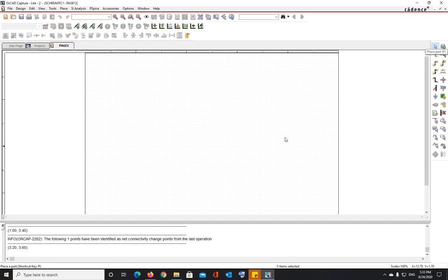And as I was telling you, if you initially chose schematic instead of PSpice AD, just copy your circuit, open a new project, and once your page opens up, you can paste your circuit. Copying is as simple as selecting the whole circuit, either using your mouse, as I will show you, or just pressing Control A, and then Control C copies it, or right click and choose copy. Then bring your mouse here, and Control V pastes the circuit, or right click, paste. So you will not have to recreate the whole circuit.